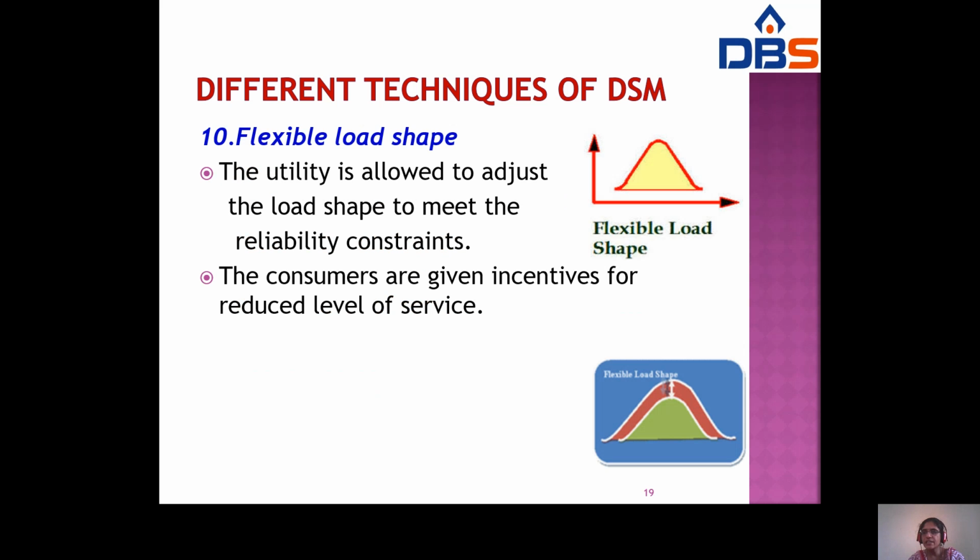So these are some of the techniques in DSM: time of day pricing, multi-utility power exchange models, load management, load priority techniques, peak clipping, peak shifting, valley filling and strategic conservation.